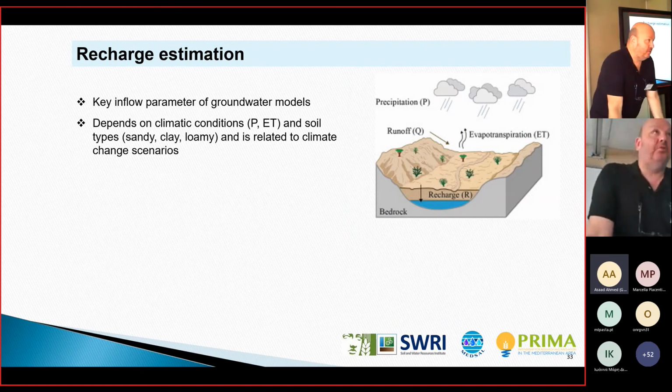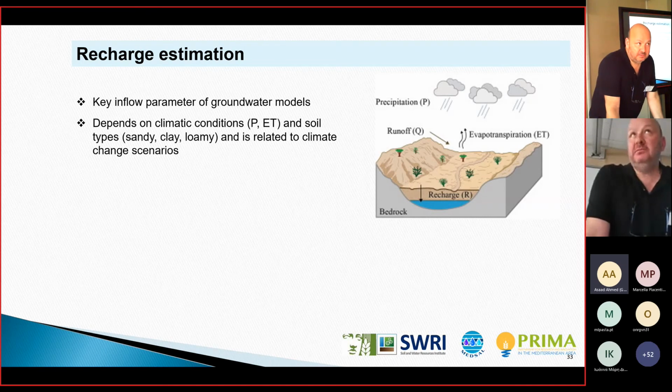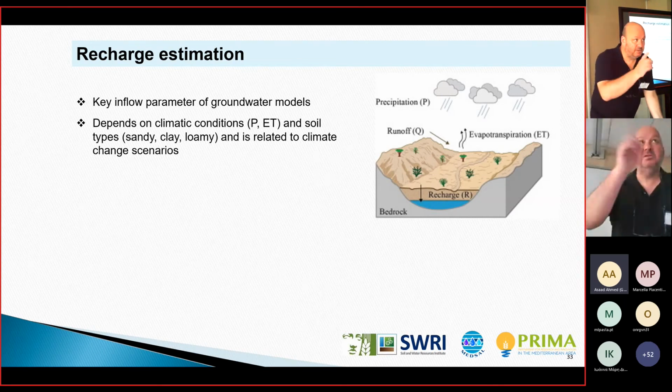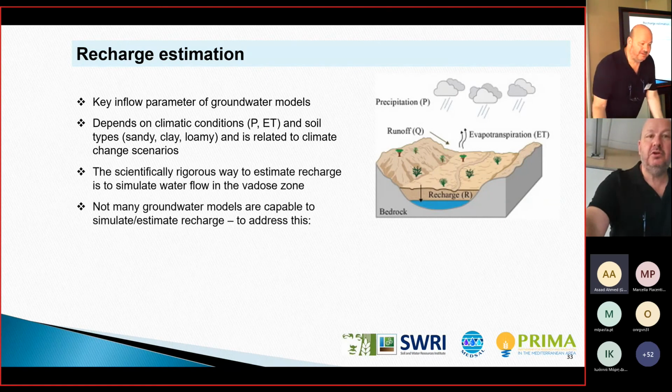Another parameter very important for the groundwater model is the estimation of the groundwater recharge. It's a key inflow parameter for the model. And the recharge depends on climatic condition, precipitation, evapotranspiration, and the soil types. It is sandy, clay, or loamy soil type. And it is also very important because it is related to climate change scenarios. So if you would like to use the groundwater model later in a climate change scenario, then you should consider very carefully from the beginning which method you are going to use to estimate the recharge.